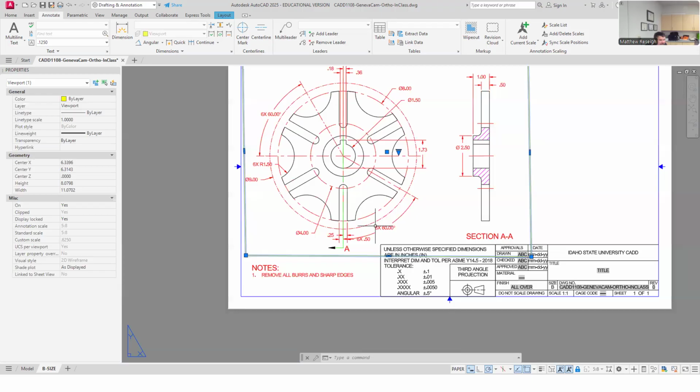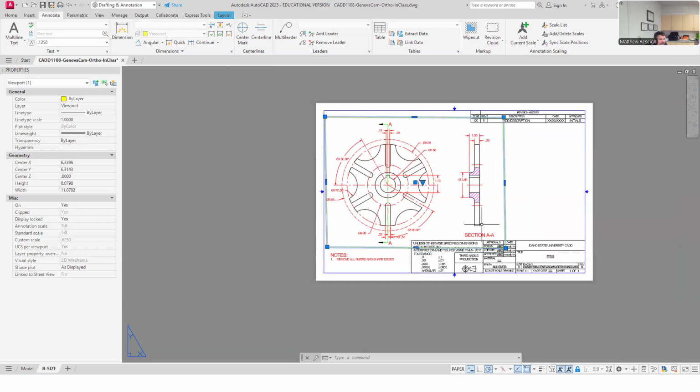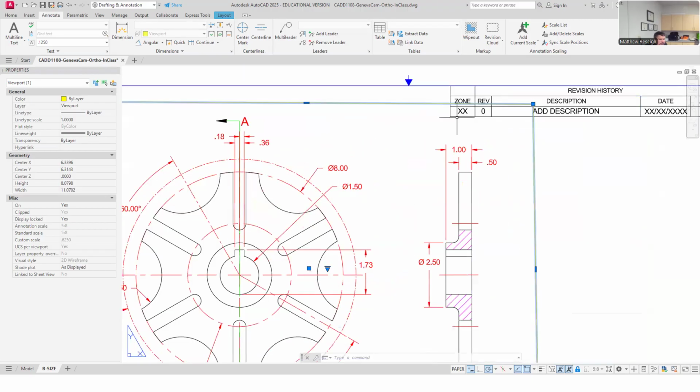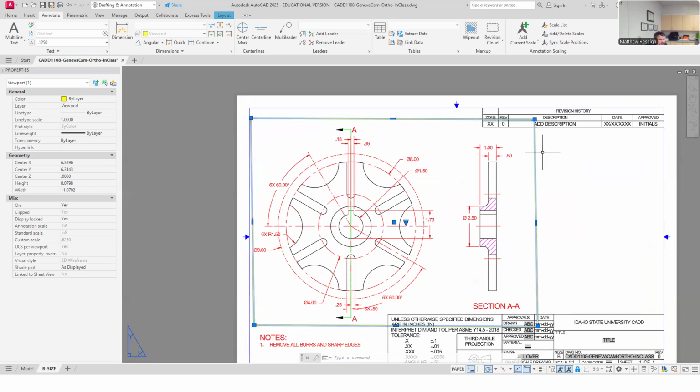I've got to have it here. If I can't bring my section heading down lower into my title block, and I don't want to bring this up higher because I do want to leave room for my revision block to grow, then to me, this is going to work. I'm just not going to be able to get my section low enough. But it's not the end of the world, because in the remove section, I would move that to a different place on the sheet and its heading would follow. Its title, I should say.